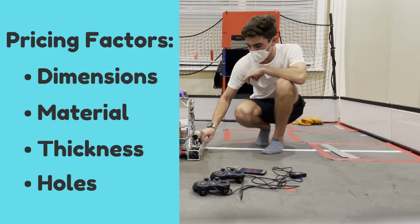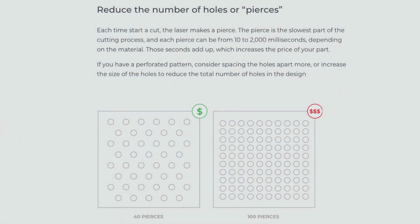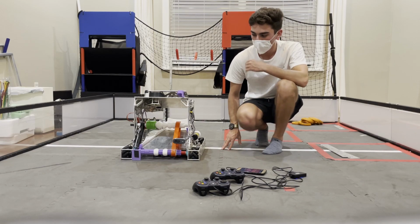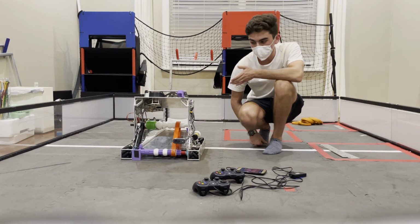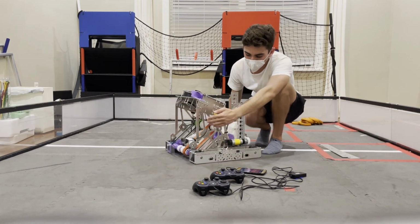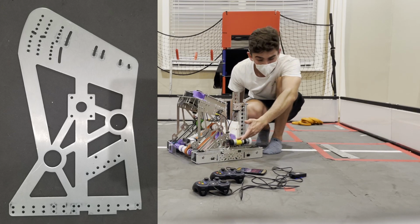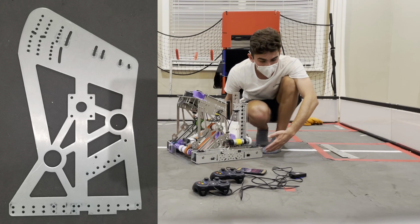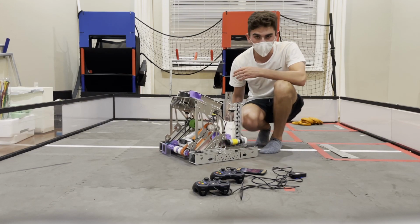That's probably, at least from our experience, the biggest factor: if you put fewer holes on your parts, it is going to cost less money. That's just because adding more holes is by far the longest part of the manufacturing process. So even if you have to keep the footprint of your part the same, which on a robot you usually do because things have to connect, you can usually cut back on holes somewhere. Like here, we have a lot of pocketing that we didn't necessarily need, but it saves us a lot of weight, which we think is more important. Same thing here. We have all of these holes that we want for mounting options, but if you don't need those, then that will save you a lot of money as well.